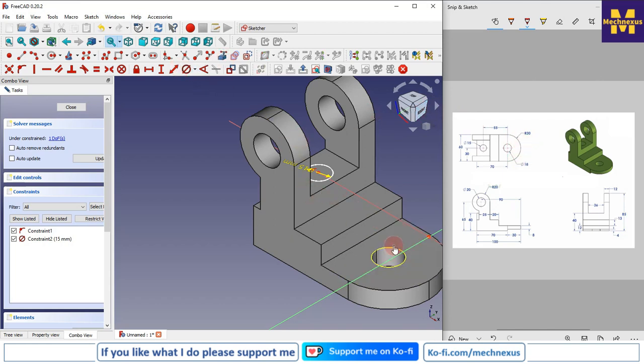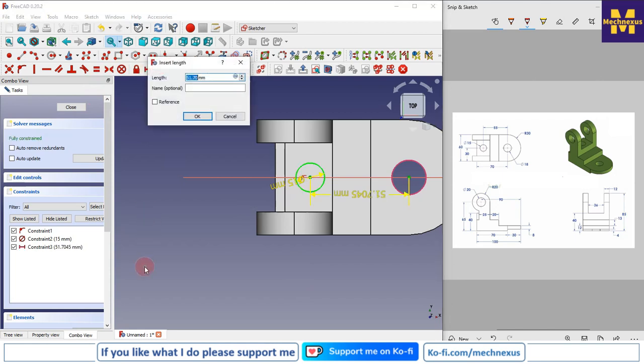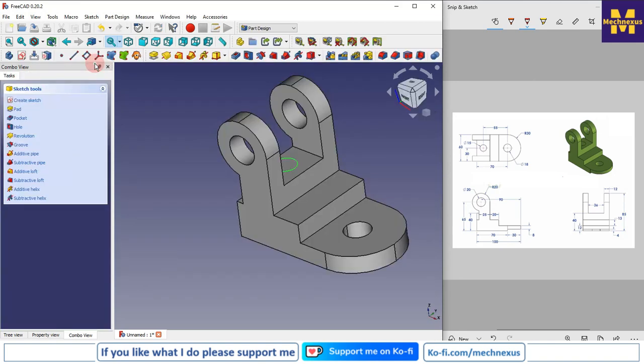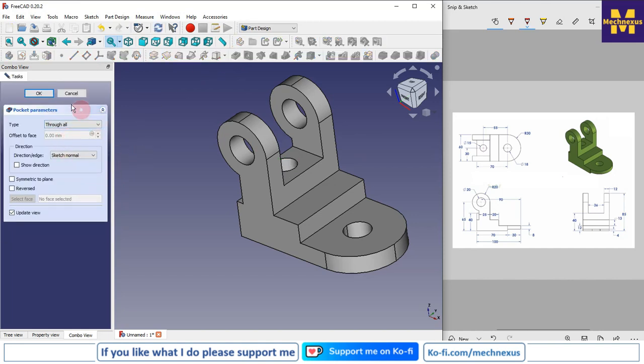So I will project this edge, I will select this point and this center and give the dimension 55, and I will close it. And it is a complete material removal, so I will go with a cut and say through all and say OK.